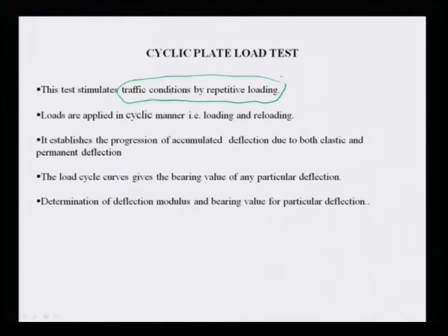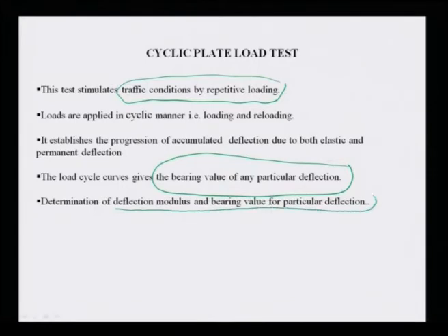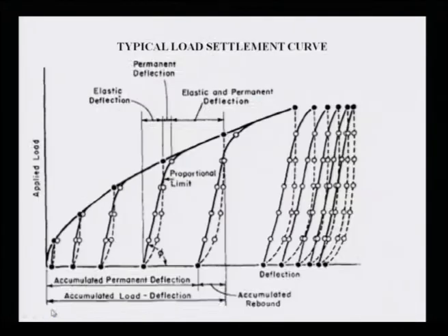The load cycle curves give the bearing value at any particular deflection. So, determination of deflection modulus and bearing. The idea of doing the cyclic plate load test is to find out the deflection modulus and bearing value for a particular deflection. Now, if I show it, this is a typical load settlement curve.